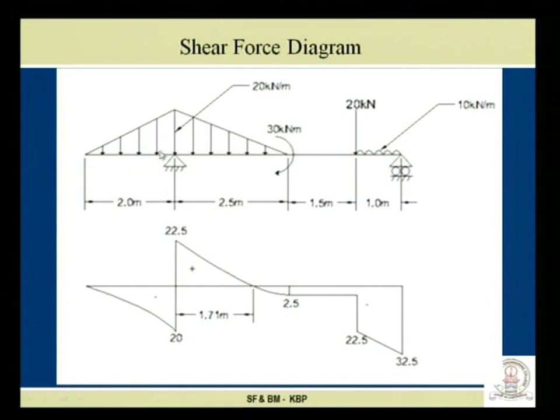Let us establish the relations corresponding to loading with the shear force, and then we will proceed further with the bending moment. Refer to the figure. As the UVL is acting over a span of 2 meter, the shear force diagram changes by a parabola. Next observation: at a point load or at a support, there is a sudden change in the shear force diagram.